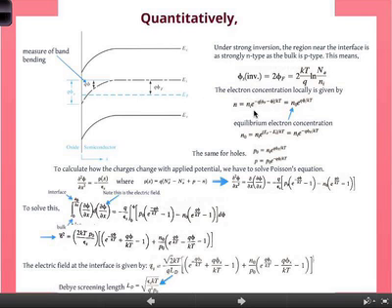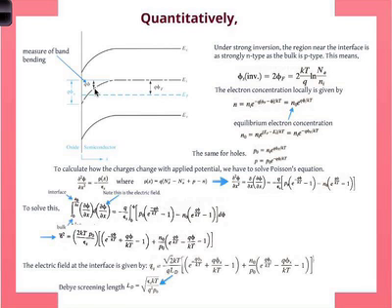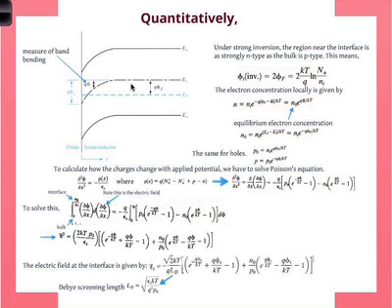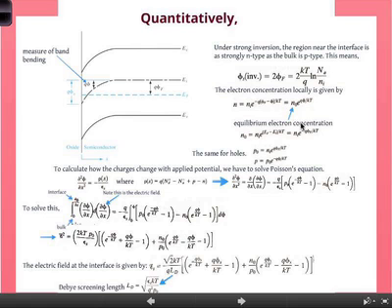Now the electron concentration locally, we can calculate that as essentially n. The electron concentration is given by that term and can be written as n_0 e raised to phi, which is this local difference between the Fermi level and the local intrinsic level and the bulk intrinsic level. So as the bands bend, the electron concentration increases. As this phi increases, there are more electrons exponentially, where n_0 is the equilibrium electron concentration.